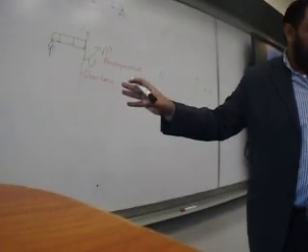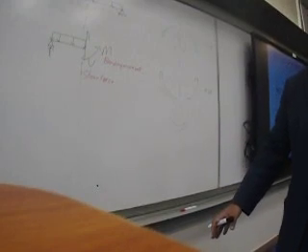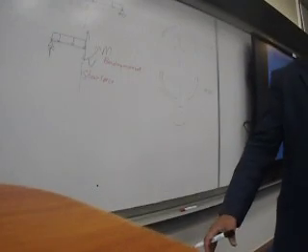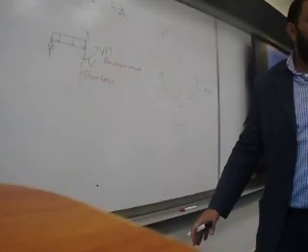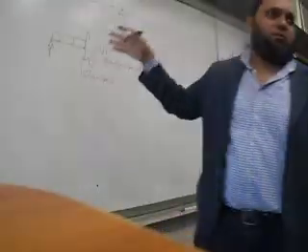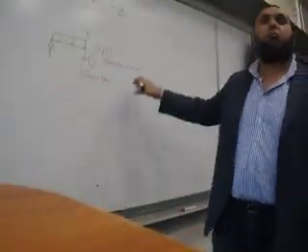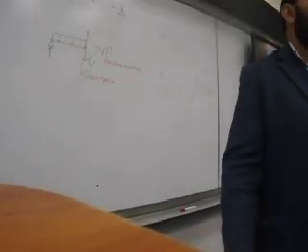I made a cut. So when I'm cutting, there is something that was not seen before. I am seeing it now, which is what I had here as internal actions: an internal force called the shear force, and an internal moment called the bending moment.